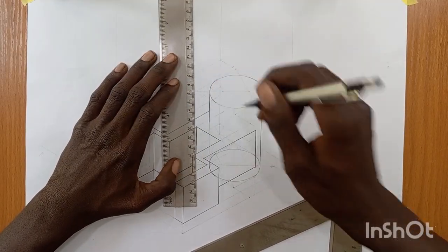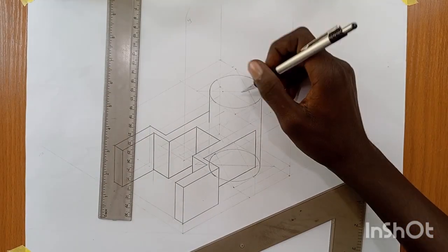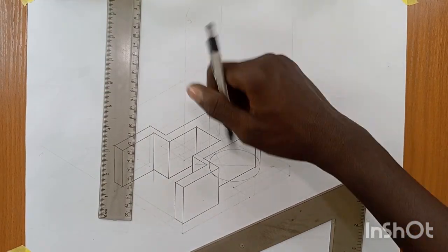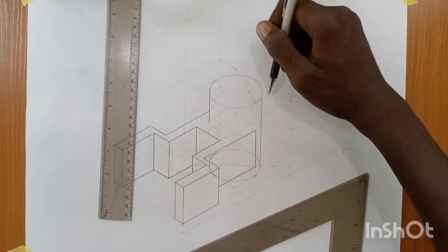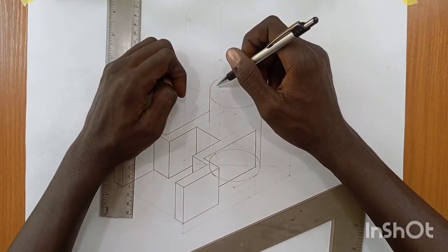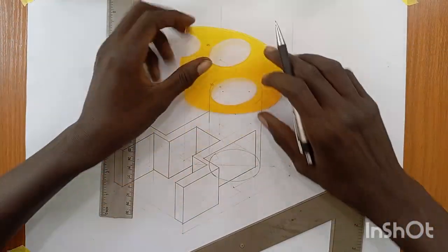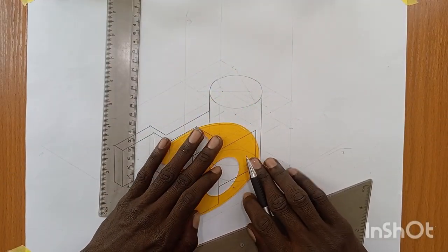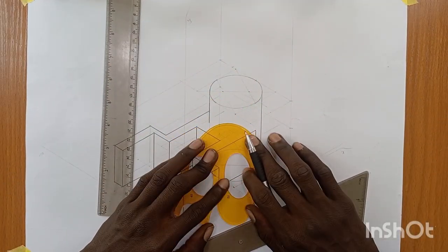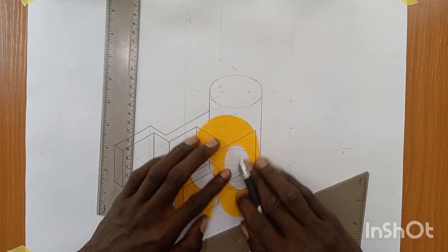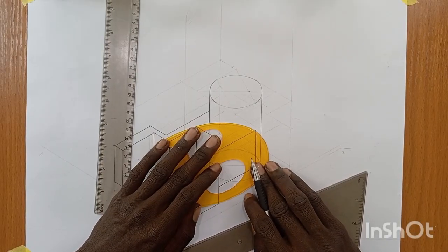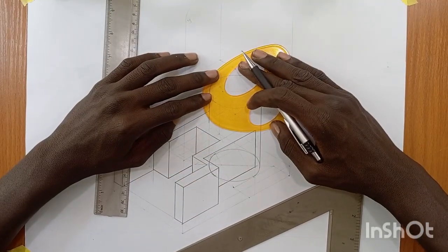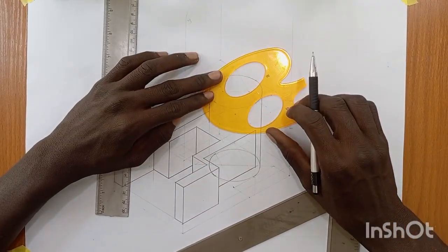Right? So ideally, as we've done in one isometric, you are supposed to draw half square here in order to do your ellipse, to connect those points like this. But I don't have the time to do all those things. Therefore, we are going to use a maneuver to pass through this. Let's just connect this using a set square. Let's connect it to a French curve. So sorry, like this. We connect this like this. It's going to give us what we want.